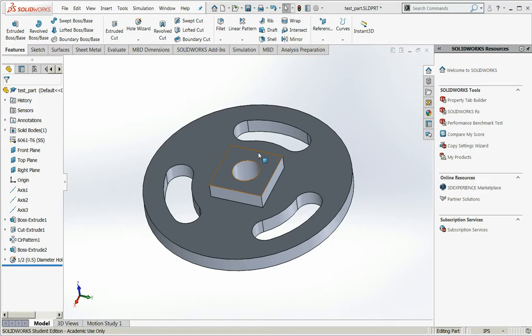The other thing I want you to notice is the orientation in the coordinate system. So X and Y are representative of where the milling table would be, and Z is in the direction of our tool. So if you can imagine, we're going to have some cutter that comes down and clears out that pocket. You want that cutter to be parallel to the Z-axis.